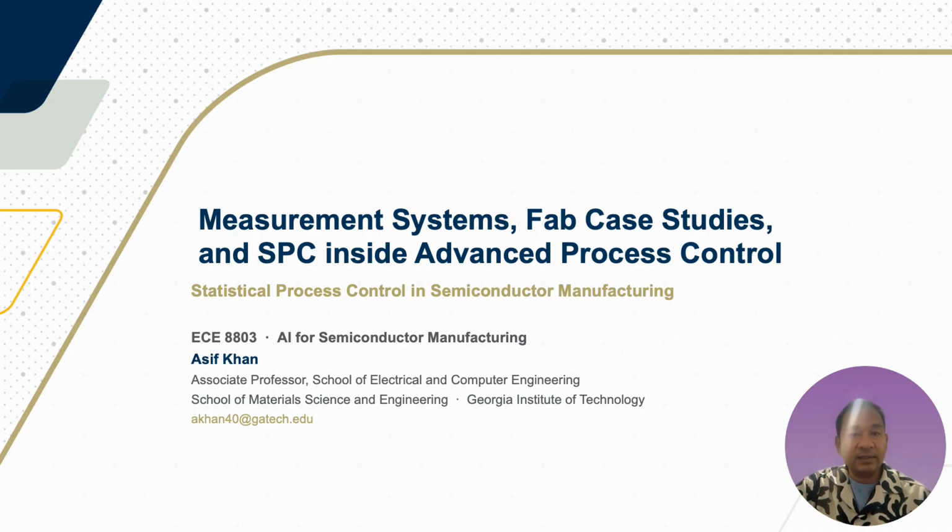Etch rate, CD, overlay, each breaks a different assumption. Third, what happens when the process is being actively controlled and when there are 300 sensors instead of one. That last part is the on-ramp to the rest of this course. Today has less arithmetic than the last two classes and more judgment. The recurring theme is that the obvious thing to chart is usually the wrong thing to chart, and the fix every time is to model what you want to understand and chart what is left over.